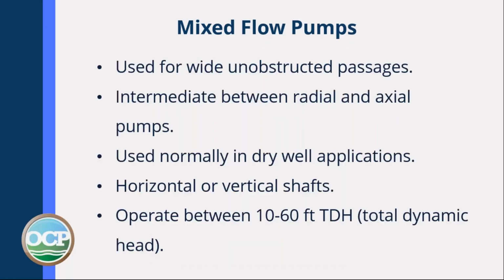Mixed flow pumps are used for wide, unobstructed passages. They're the intermediate between radial and axial pumps. They're normally used in dry well applications. They have horizontal or vertical shafts and operate between 10 and 60 feet of total dynamic head.